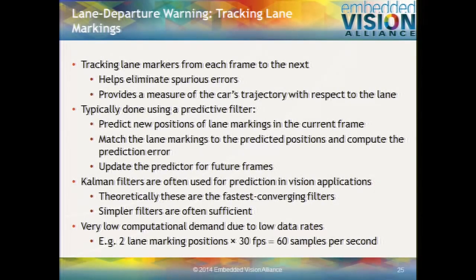For example, maybe the imaging conditions are marginal, and so every third frame we don't get a clear edge on a particular marking. Well, it's not helpful to us if we're oscillating back and forth between it's a lane marking, it's not a lane marking, it's a lane marking, it's not a lane marking. We've got to decide. And one way we can decide is to look over time and say, well, in this frame it was here, in this frame it's here, in this frame it's here, here it's missing, but it's back in this frame. Yeah, I think it's a lane marking, for example.